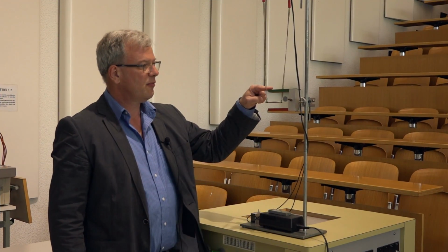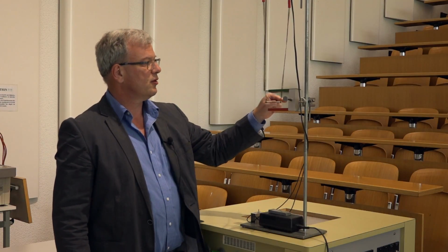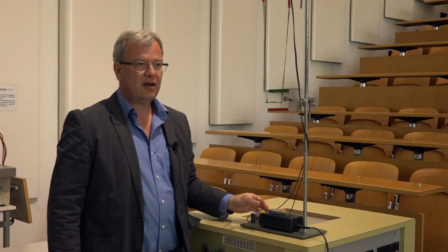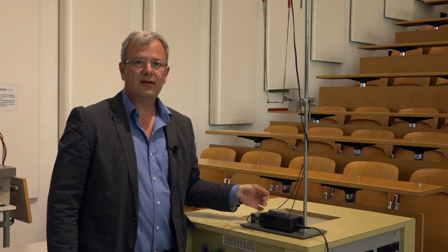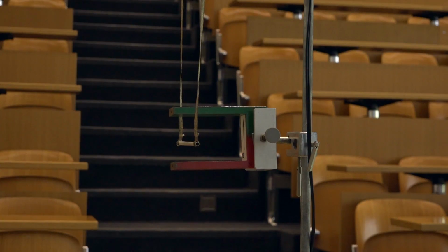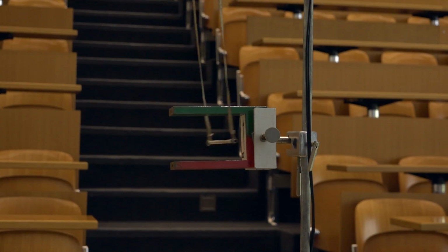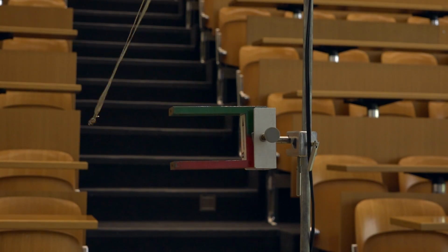Okay, in this experiment we have a permanent magnet here, and we'll be running a current through this structure. I will turn on the current and it will invert its polarity, and you can see the force that the magnetic field exerts on the conducting structure. First in this way, it's attracted towards the right. And now if I reverse the polarity, it is pushed in the other direction. That's a demonstration of the Lorentz force that's exerted on the structure that carries the current. This is what we have also in the MRI experiment.